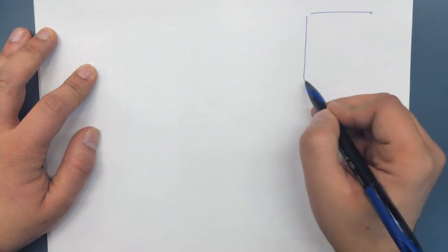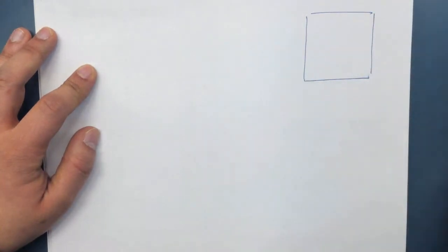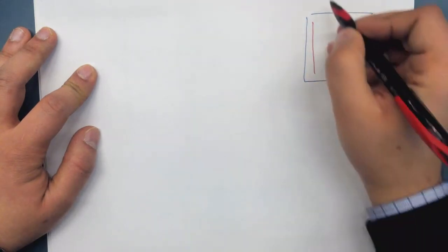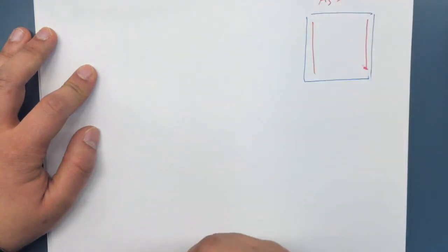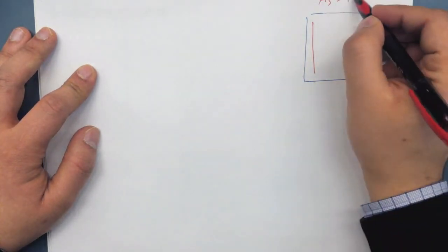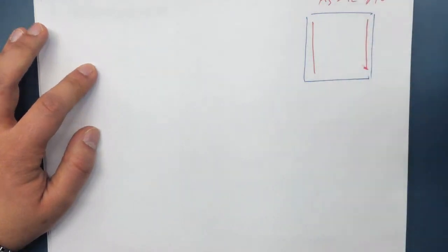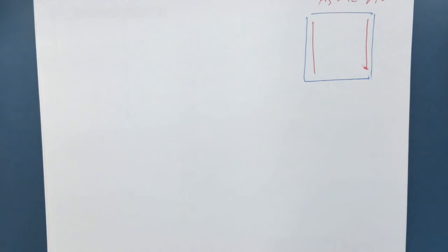Although the problem doesn't show this, it's not kind of accurate, but the steel that we have here and here combined is equal to 12 number 10. It shows just 8. But don't look at the graph. Look at the information that you're getting.